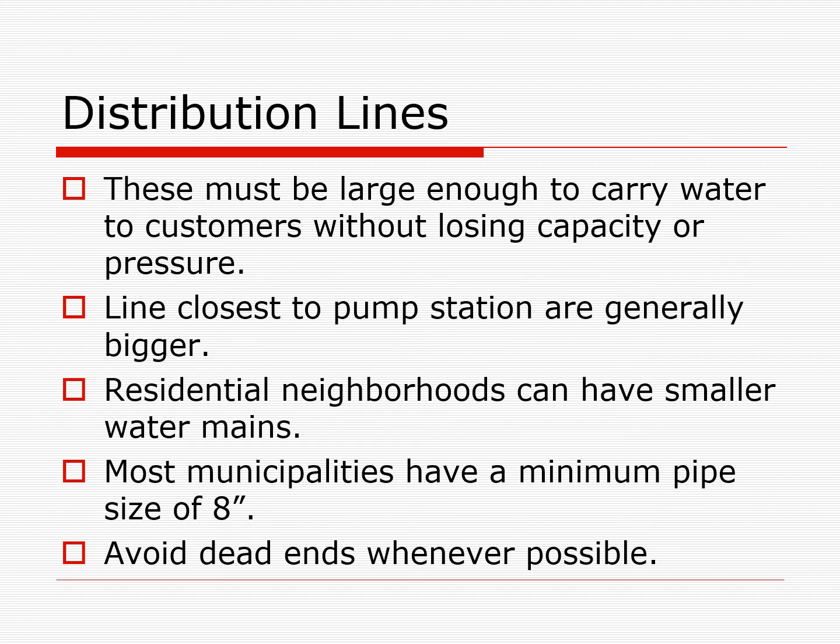My distribution lines must be large enough to carry water to customers without losing capacity or pressure. The lines closest to the pump station are generally bigger.